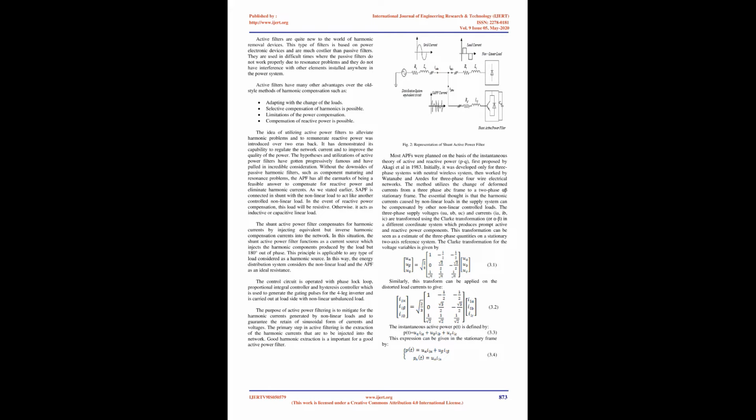CBs and fuses. If the distortion results in a higher level of di/dt at zero crossing, load interruption can be more difficult than for a sinusoidal waveform. Fuses malfunction under the influence of harmonics. Watt-hour meters. Induction discs are calibrated for accurate operation on the fundamental frequency only. Harmonics generate additional torque on these discs, triggering incorrect operation and improper readings.